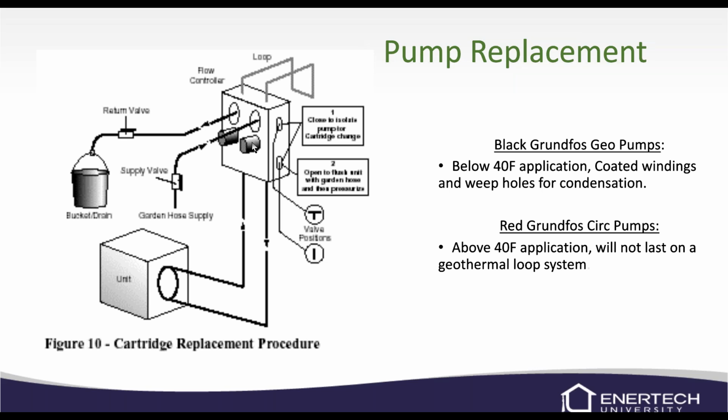Basically, once you put the pump back on here, you're going to have a garden hose that supplies some water so you can fill this back up, and then you can push the air back out on the return side.